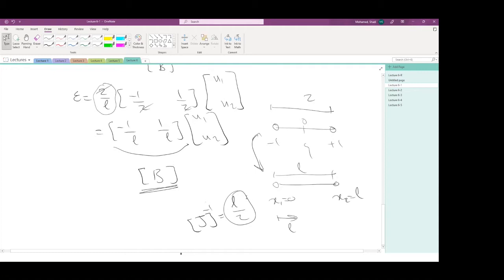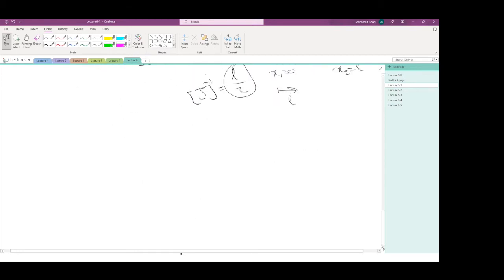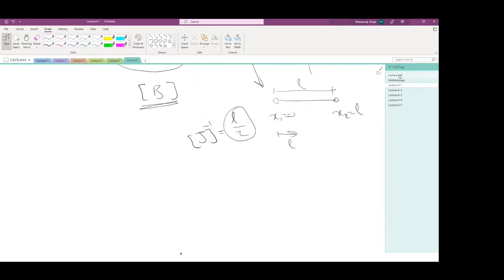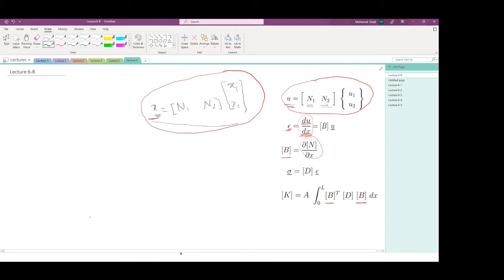Now, the second application we will come to when we need to find the integral. Now, you remember here, we have this step completed. And with this step completed, we have the B matrix. If we have the B matrix and we have the strain, we immediately get the stress. The stress, this is just the elasticity modulus. Elasticity modulus has no different meaning in local or global coordinates, it is always going to be the same elasticity modulus.